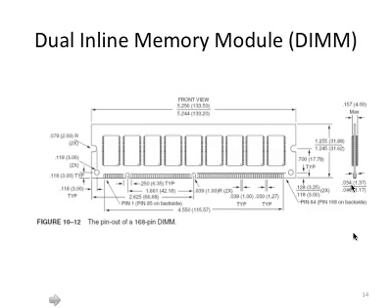If you look at it from the side, you see this PCB has two sides, and each side has a number of memory chips. For this particular one, one side has 84 pins, and the two sides have independent pins. So together you have 168 pins out of this dual inline memory module.